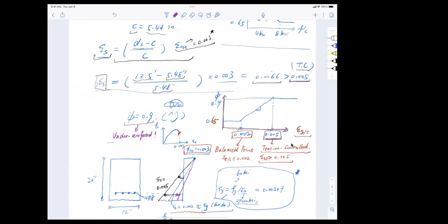I believe you said it makes us happy. Yes, so that is a good thing. You are absolutely right. So what it tells us, we want our beam under reinforced, preferred under reinforced, so we can utilize the strain in the steel, full ductility. What does that mean? That means we have time to run. We have time to escape when something bad happens.